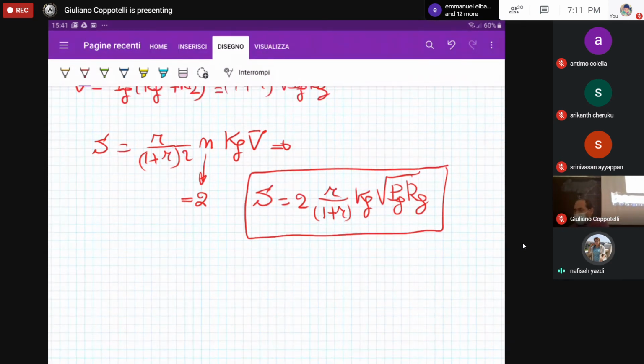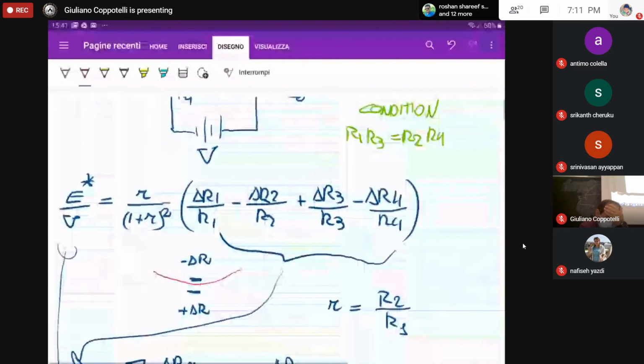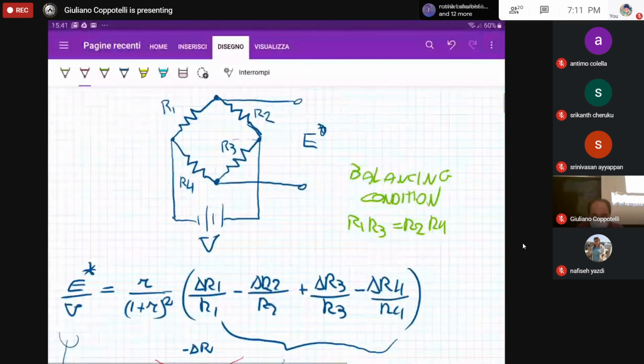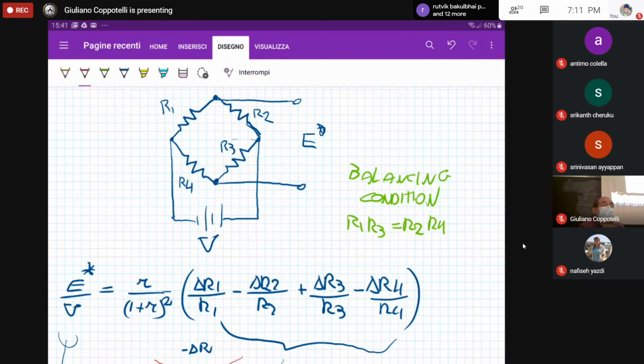Can you explain one more time about temperature compensation? I didn't understand. If you go back to the first equation that I wrote today, if you put one strain gauge in leg number one, R1 is equal to Rg, the strain gauge resistance, and you bond that strain gauge on the structure. Then let's assume you have an additional strain gauge that you can put on leg number 4.